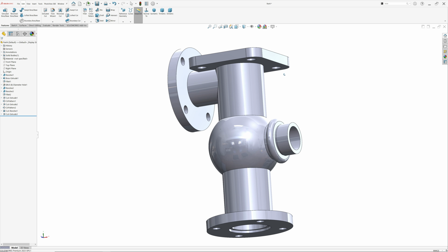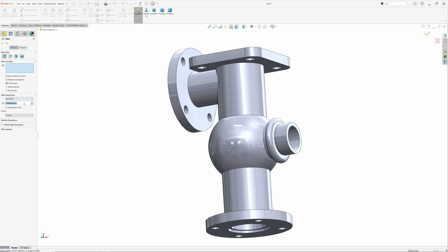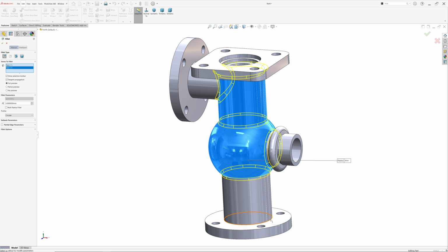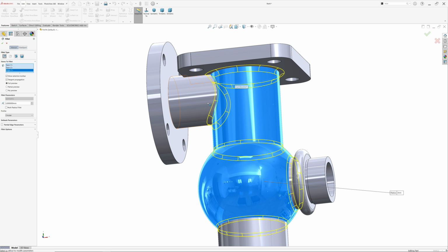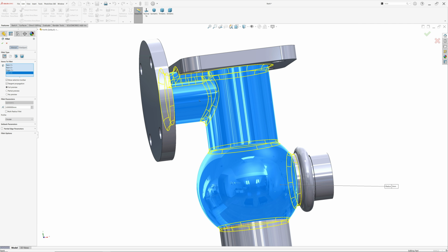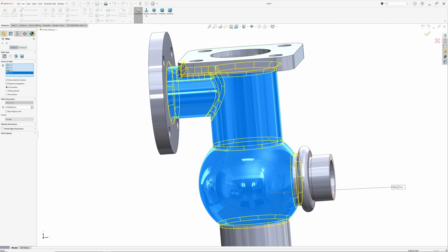Let's apply some fillet, constant type fillet, size 3 millimeter. Now I am going to select one, select this face and this edge. Fine, here we covered all. Now select this face. Look, this is also covered all. So no need to define each and every time. Okay.